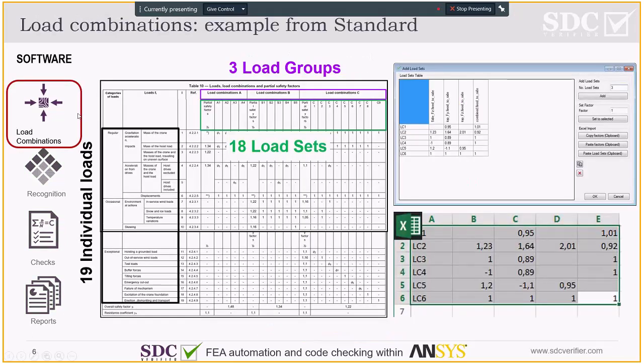First of all, we're going to review the load combination. Many standards have complicated load combinations to be implemented for checking. There are some regular loads, some occasional loads, and exceptional loads, with certain partial load factors and with a safety factor to be put on. So we are able to create these combinations easily.